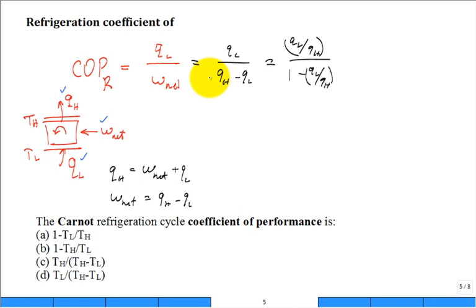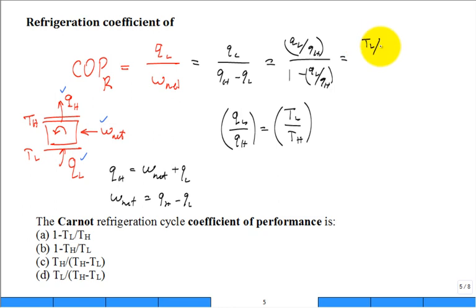But at this point, if it's all reversible, we could go back to Clausius and his inequality, and then it's an equality if it's completely reversible, and we can replace the ratio of Q's, QL divided by QH, by a ratio of T's. I forget what chapter that's in. Maybe end of chapter 5, beginning of chapter 6, and that inequality becomes an equality when it's completely internally reversible. So this can be now TL divided by TH.